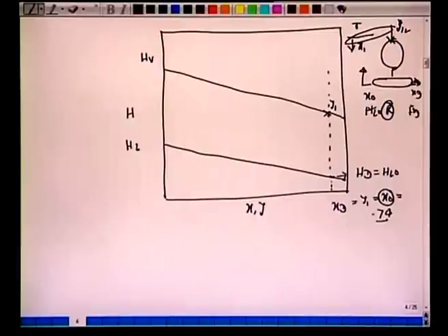All right. Maybe there is a tie line here which we have to read from the xy diagram to obtain this x1 on this saturated liquid. This would be now x1, and the composition of this x1 will be HL1. So we have HL0 is the enthalpy of this stream which leaves here, and this HL1 is the enthalpy of the liquid, saturated enthalpy of the liquid saturated at this temperature T. So the T and Tc, they are different. You must understand this, otherwise we make a mistake in marking the enthalpy point. So this is HL1 here, and we have HL0 here.